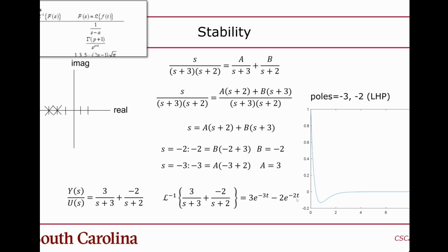So that's an aspect of control theory: when you're designing a controller, that's really what you're doing in a way, making sure those poles are in the right spot. Now, the problem, I mentioned this last time, is that just moving the poles often isn't enough, or isn't a great way to do it, because even though the system may become stable, it's not necessarily going to be a good controller.